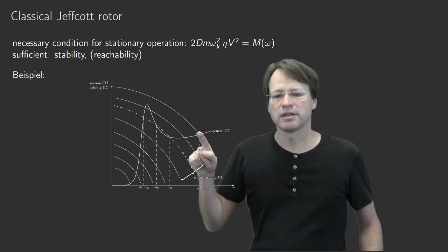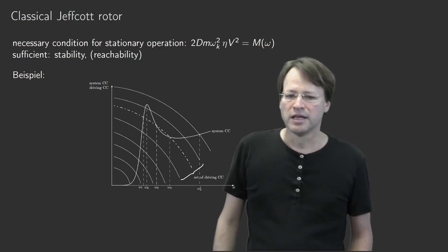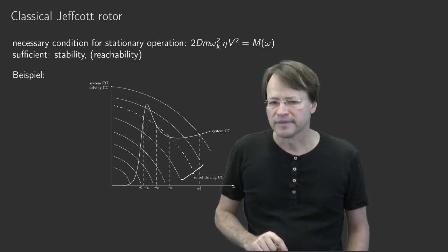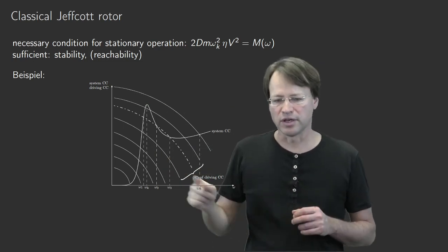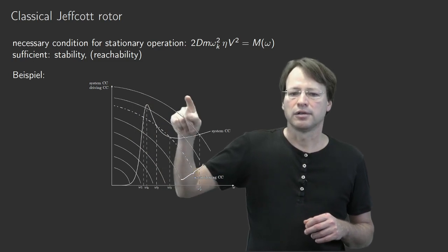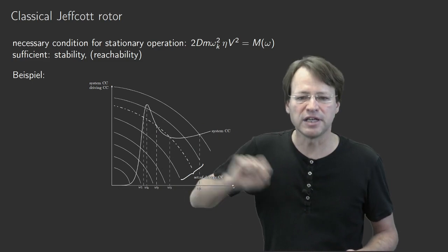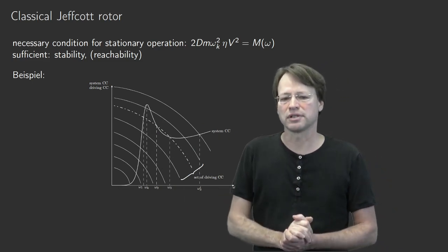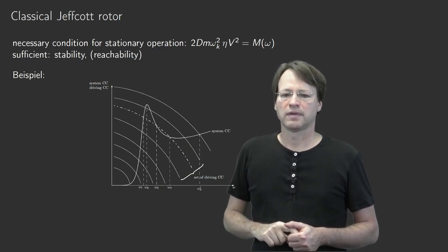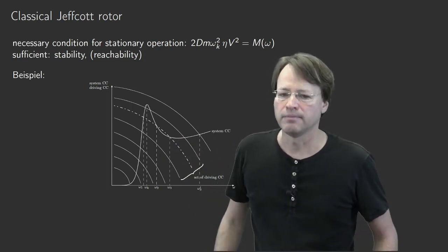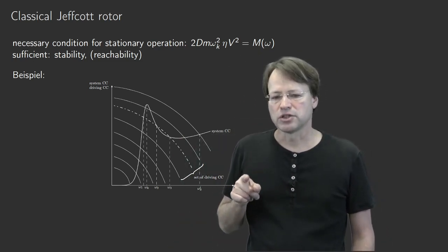And then I fall back to that balance between my old driving torque and my system characteristic torque. And now the question is whether that state is stable or not. So what we learn is we need an additional driving characteristic curve to get out of that very dangerous situation where we get stuck close to resonance. Now we are here.